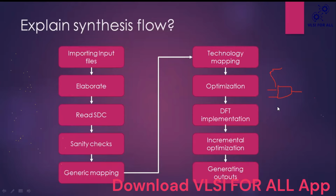After this technology mapping, the tool does optimization. What is optimization? Optimization means, for example, there are 100 timing paths in our design, but 10 paths are violating setup and hold. The tool will try to fix those timing violations.